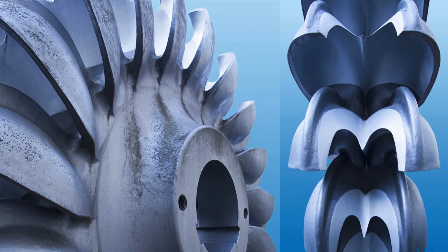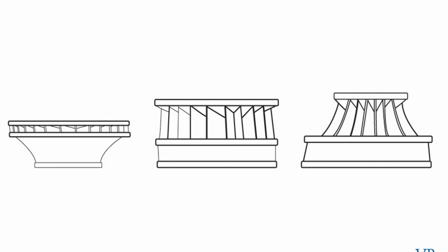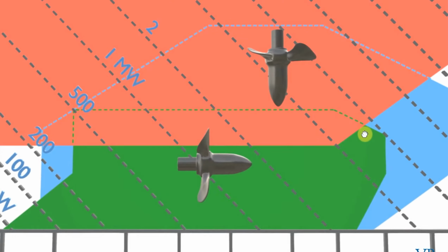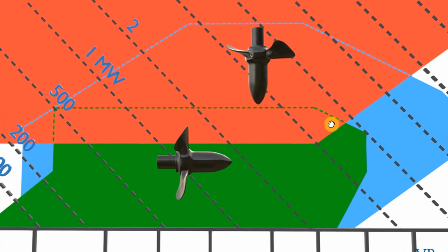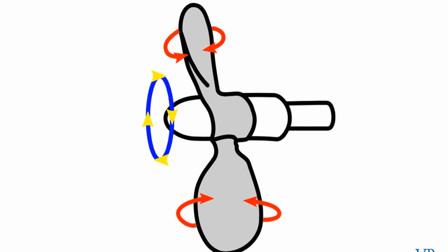The Francis runner, generally it will have this shape, although the actual geometry of the runner depends upon the speed and the pressures in which it operates. The Kaplan runner is very much like a normal propeller, except the blades can be varied and their angle of pitch can be changed. So that means these blades can be adjusted and they will rotate either to the right or to the left. And that is a variable pitch propeller or a control pitch propeller. And you'll see that in action, and we'll talk about it once again just to refresh your memory when we look at tidal power generation.